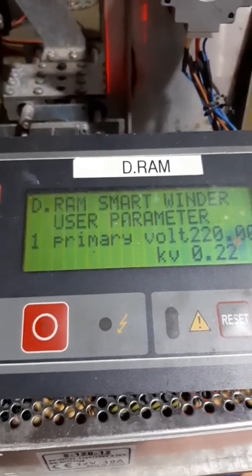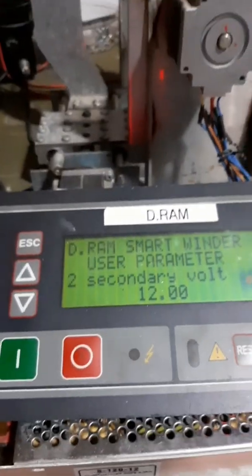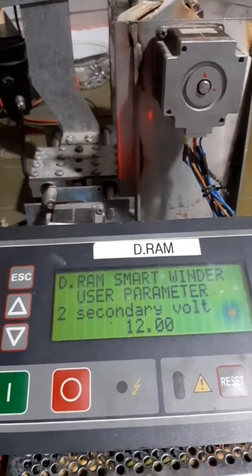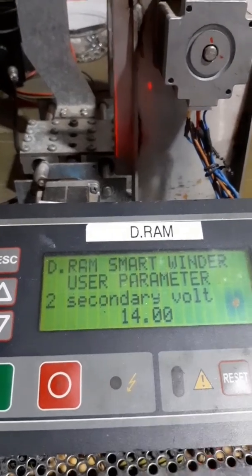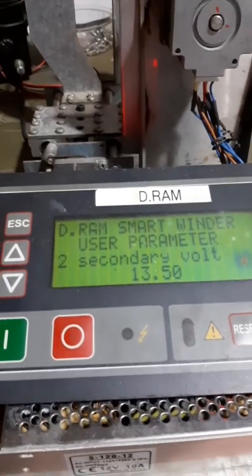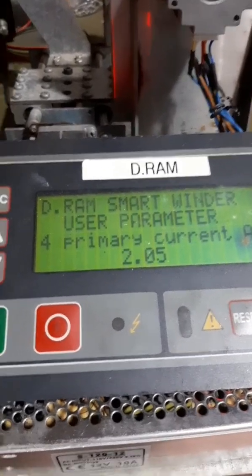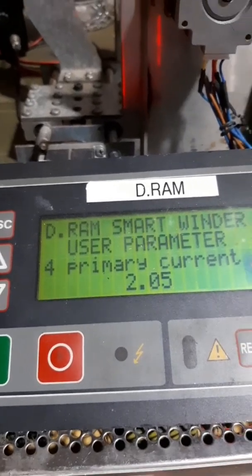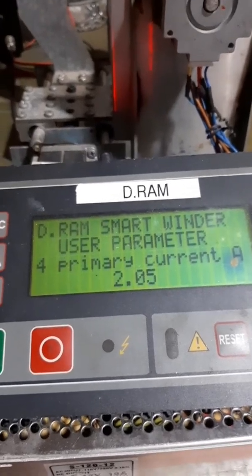Second, I have to set the secondary voltage. What is your secondary voltage necessity? It's 12 volt or 24 or 110 or something. I can change this to whatever you want, 13 or 14. For example, I have 13 volt, 13.5. And another parameter is the primary current. What is your primary current? The machine will automatically give you this parameter. We should not update it. The machine will automatically calculate it by your kilovolt and your given voltage.